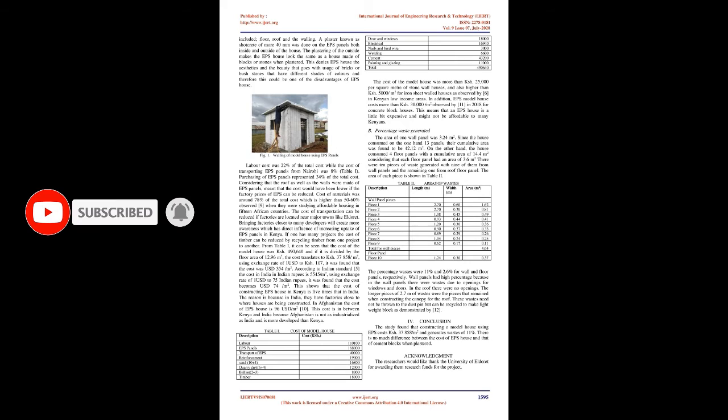During construction, the wastes generated as a result of cutting EPS panels at the door and window spaces, and construction of the canopy for the roof, were measured by taking the length and the width of each piece that remained. This was done for both wall and roof floor panels.